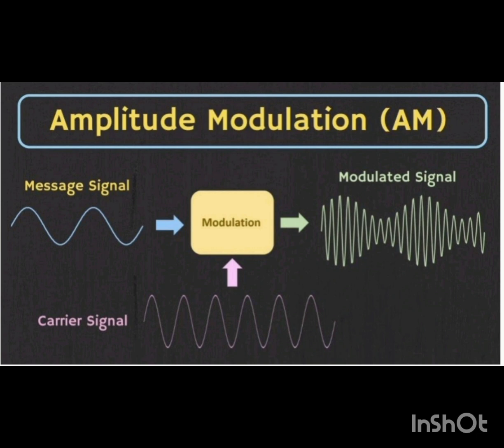Thus, when there is temporarily no modulation, the amplitude of the carrier is equal to its unmodulated value. When modulation is present, the amplitude of the carrier is varied by its instantaneous value. The situation is illustrated in the figure, which shows how the maximum amplitude of the amplitude modulated voltage is made to vary with changes in the modulating voltage. The figure also shows that something unusual, distortion, will occur if Vm is greater than Vc.